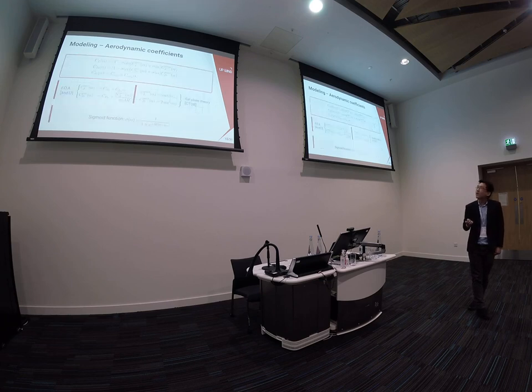So we use a blending function to match the regimes. This sigmoid function here is like a step function from 0 to 1, but the place where the step occurs is at alpha 0. Okay. So for the prestall regime, we use the textbook formula in the Fundamentals of Aerodynamics. And for the poststall region, we see that the flat plate theory is enough to fit the poststall regime.